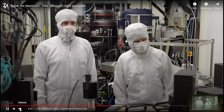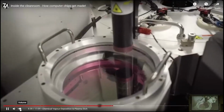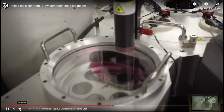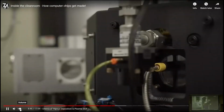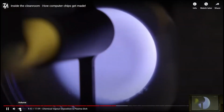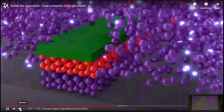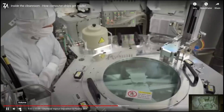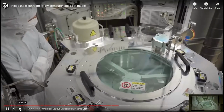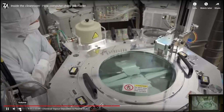This is a reactive ion etching tool. So here we are in the maintenance area of the clean room. In these kinds of tools, we etch away material, as the name says, and we do this by creating a plasma above the wafer. We have reactive gases above the wafer. They get ionized in a plasma, and the way it's constructed is such that the plasma can react with the material that we want to etch away. And the special thing about plasma etching is that we can actually control the geometry of the structure, like very steep sidewalls, or actually we can control the sidewall angle.